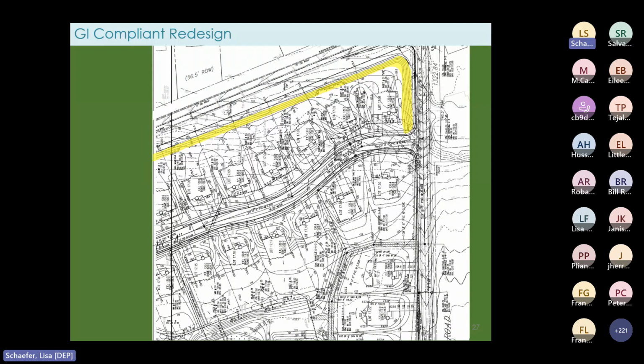So from the soil exploration map, we saw that the depths to the seasonal high water table were deep enough here. So this swale could be designed to infiltrate. And planting trees and shrubs in and adjacent to this bioretention swale would also help reduce noise from the main thoroughfare. Or you could go with a grass swale, but you'd have to check that the calculated velocity and depth of runoff comply with the design criteria. And maybe then you would add street trees closer to the main road. Anyway, this concept would have to be combined with something for other parts of the site.